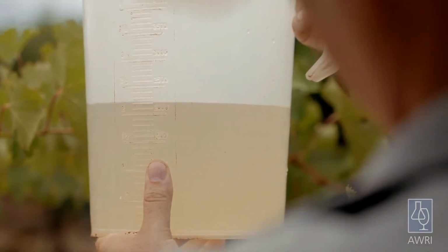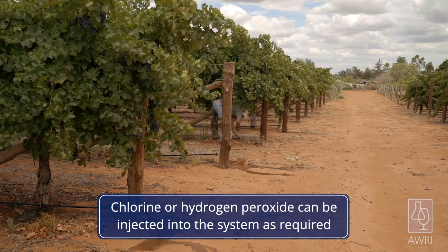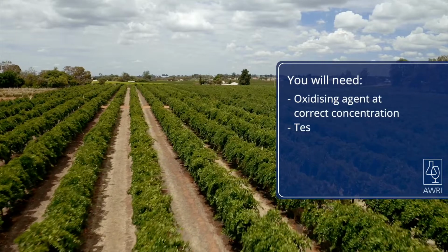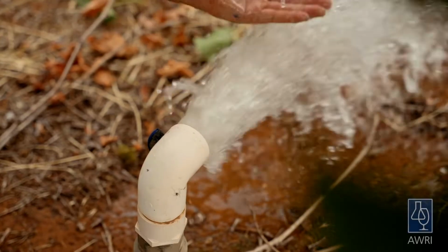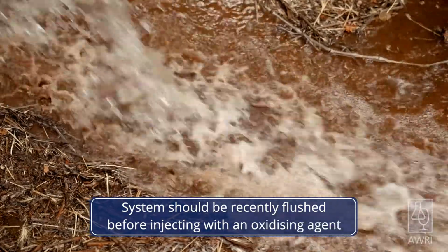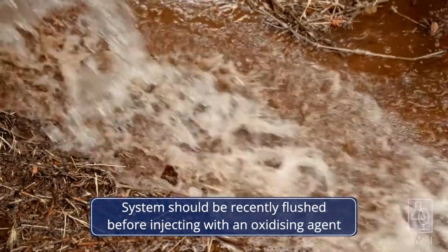If algae and bacteria are an issue, oxidising agents such as chlorine or hydrogen peroxide can be injected into the system as required. To inject the system with an oxidising agent, make sure the system has recently been flushed so the oxidising agent does not have to act on excessive organic matter.